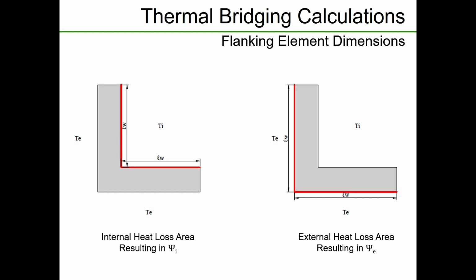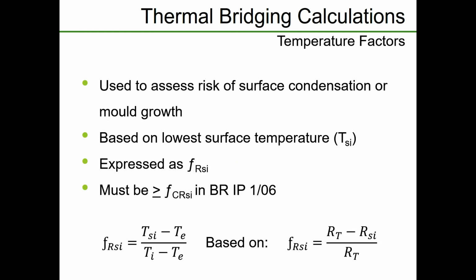In certain contexts, yes, it's a good idea to over-engineer everything and go down that route of overcompensating, and then you've got a factor of safety in there where you're bridging. The thing that passive house does is you only really calculate thermal bridges if you're reducing the insulation by more than a third, basically, of what you've got elsewhere in the walls or roof or whatever is connecting at that junction. So in that respect, that's where you may end up with different heat loss values, and it would be overcompensating on the U value side of things there. So yes, it's good practice to do that if you can, but I'd rather assess everything so I know where we're at really.